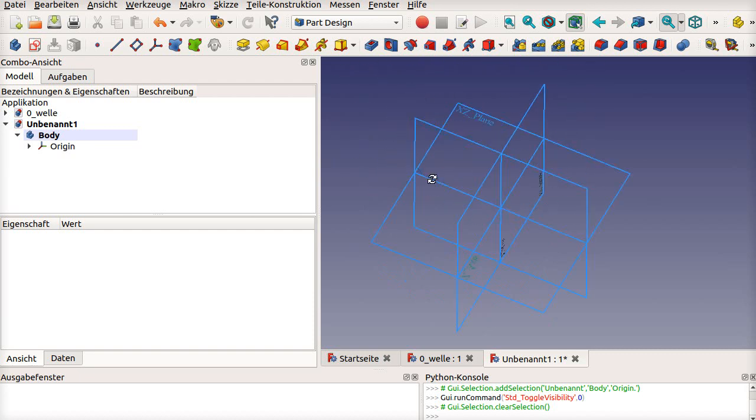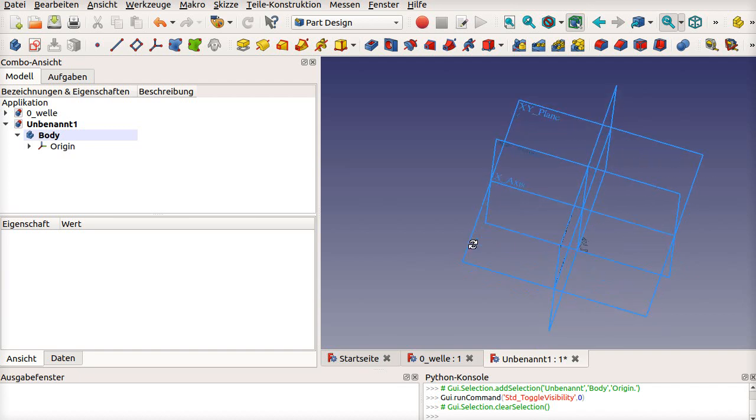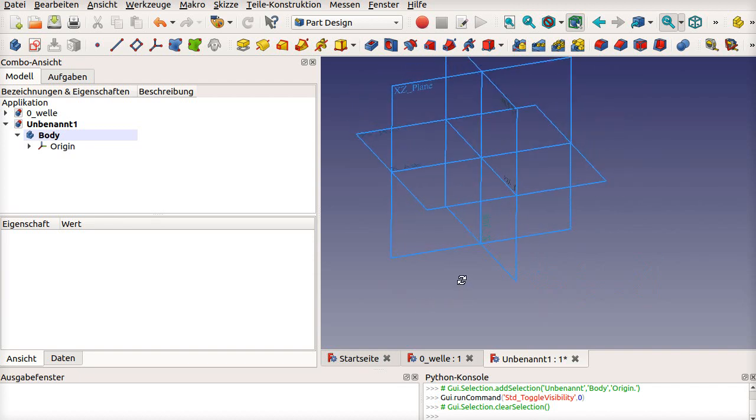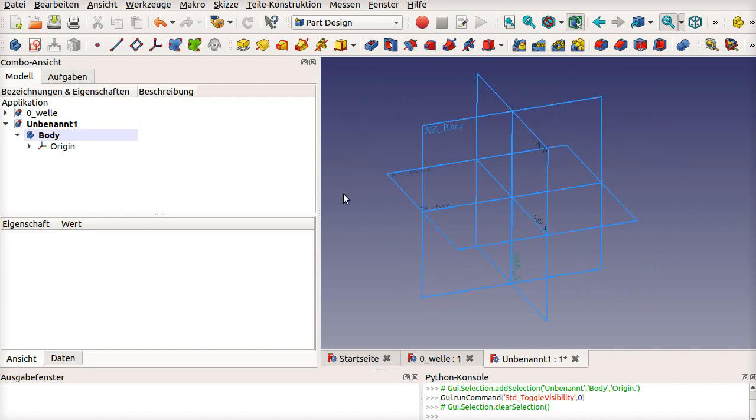And if it's a lathe part with rotation symmetry, it's best to start on the XZ plane. Of course, the machine that produces the part has this plane set up. So it's a rotation part, so let's start first with an axis to indicate it's a rotation part. The video is mainly for our students, but it's always best to follow good construction.